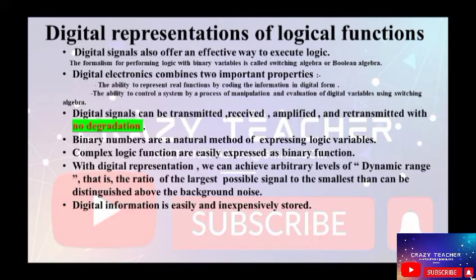Next we go into why digital signals are preferable. Digital signals can be transmitted, received, amplified and retransmitted with no degradation. Why do I say so? Because if you are transmitting some digital value, ultimately what is transmitted is a bit, 1 or 0. Suppose in my system 1 is represented by plus 12 volt and 0 is represented by minus 12 volt.